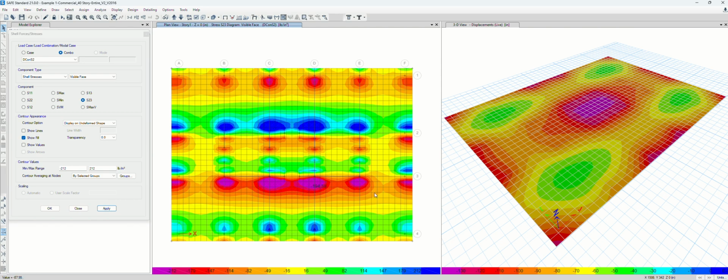Also, when you look at the core wall, your moment of inertia and section modulus, you see that our moment arm is smaller, so you get a bigger overturning moment effect, which creates bigger compression and tension coupling force.